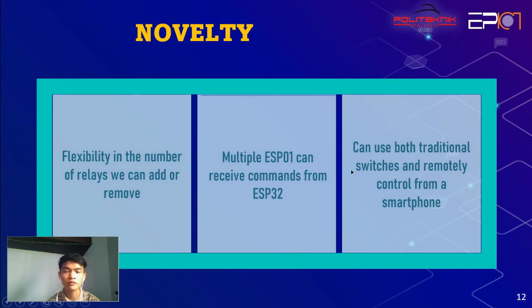We'll be continuing with the novelty. The novelty is our project is flexible in the number of relays. We can add more or remove some. The second one is we can communicate with multiple ESP01, then receive commands from a single ESP32. Then we can use both traditional switches and remotely control from a smartphone.